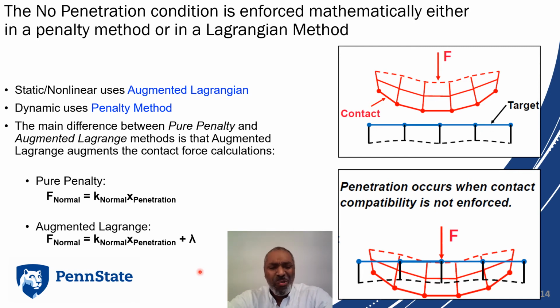And if you remember Lagrange multipliers from a differential equations class or maybe a Calc 3 class, Lagrange multipliers exist to add terms to a solution that help the solution satisfy some constraint. I won't go too much farther into it than that, but the purpose of this lambda here is to scale this force value such that you get both smoother results, you cut down on the instability, and also you have this surface track back to that surface more efficiently.